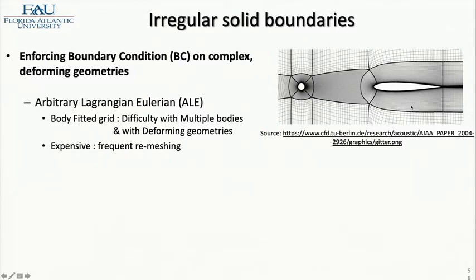The grid gets all twisted, and cell sizes start going to 0. Even if you just had two circles over here, you would have something similar, because the other circle would need a different body-fitted mesh compared to that one. And now imagine that one of them starts wriggling in time. So imagine you're trying to simulate how a fish swims behind a rock.